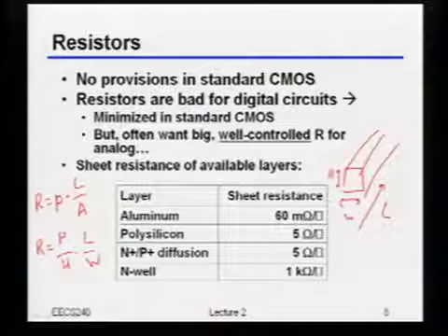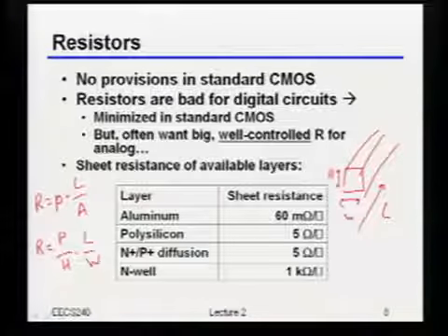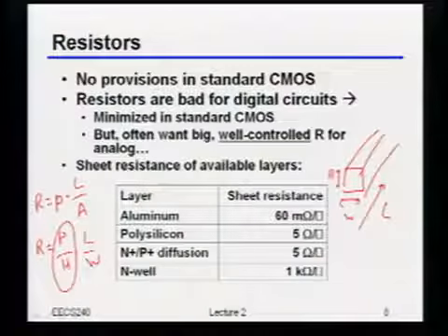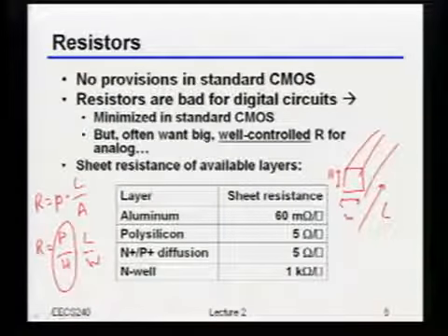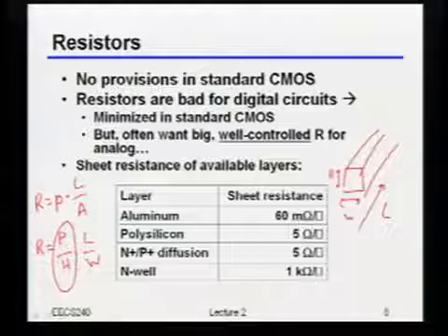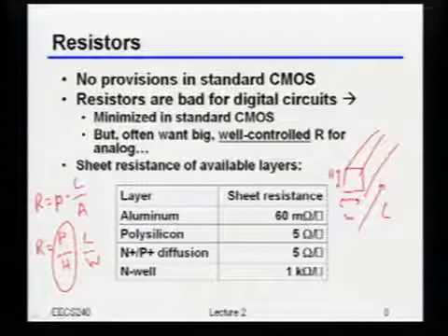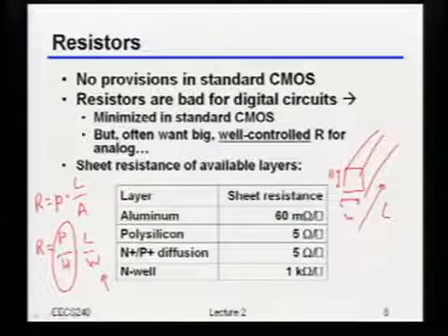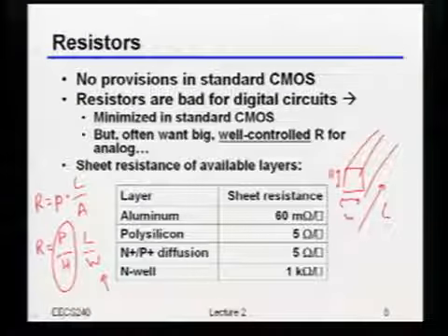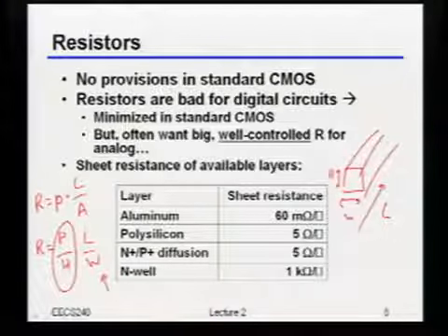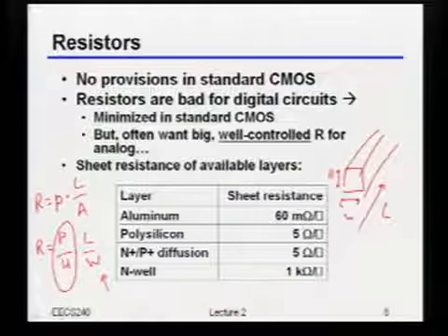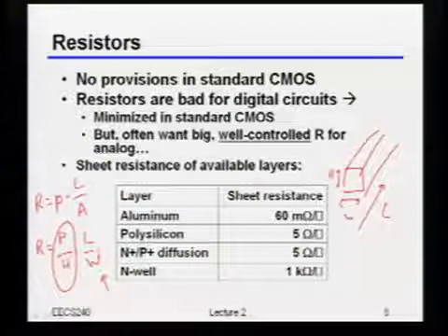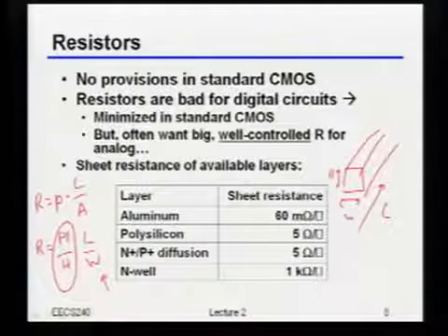Okay? So what I mean by sheet resistance, which is often referred to as ohms per square, is just that quantity right there. Because it just tells you if I was to draw a wire in my chip, I can calculate how much resistance I get just by looking at the aspect ratio. In other words, what's the length divided by what's the width. So does that make sense to you guys? Okay, perfect. So again, why is this important? Because if I want to make a big resistor, then what I really want is a fairly large resistance per square.